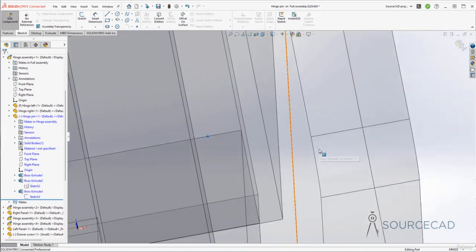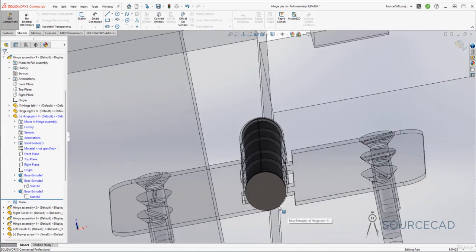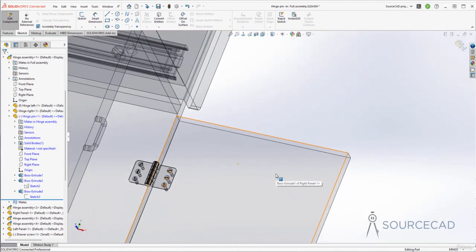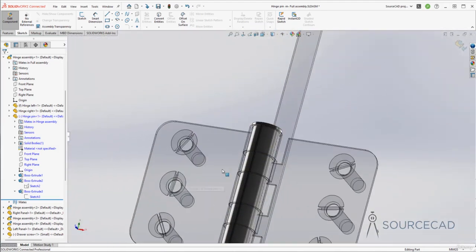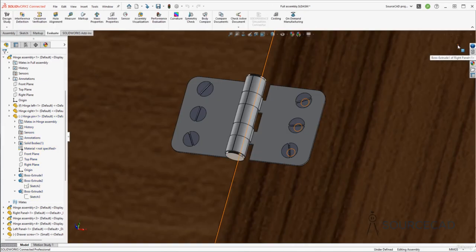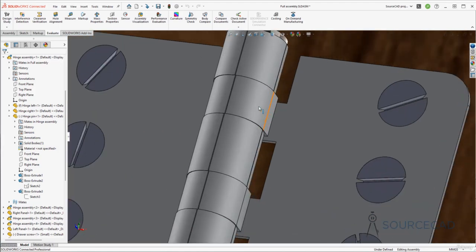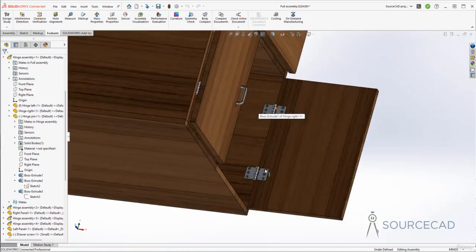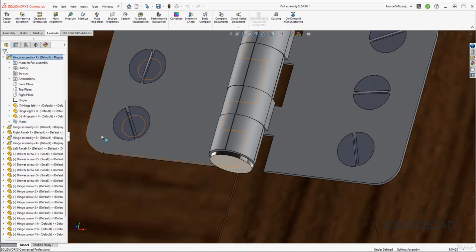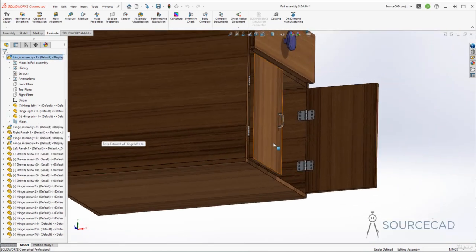All right, so we have essentially modified both the sides, this side of the pin as well as the top side of the pin. So we have modified it from top, we have modified it from the bottom. And with that, we are ready to check it. So exit out of this. Now it's smaller. And with that, all the other pins are also modified because essentially they're all just the same pins with different copies. So let's again check the interference detection.